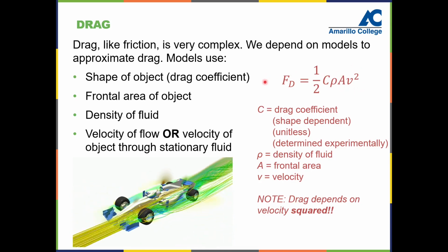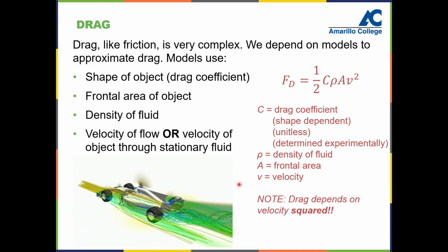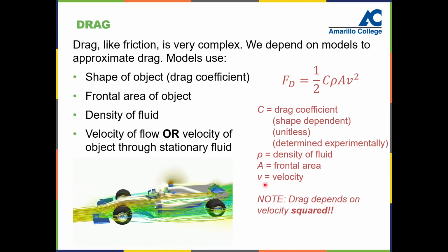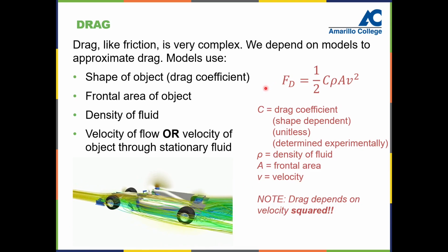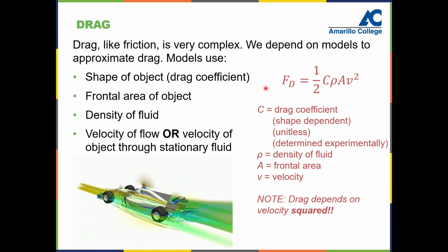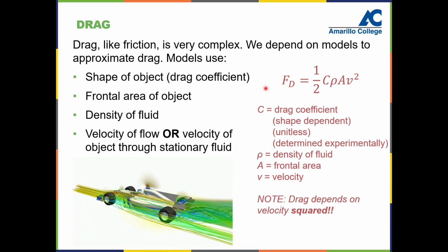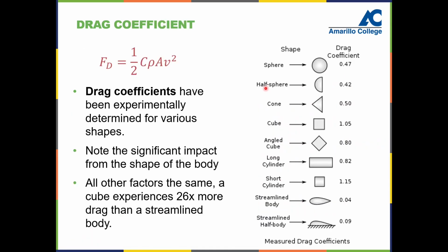So the velocity squared is proportional to the force of the drag. That means as we increase the velocity, the force of the drag increases with that velocity squared. So the force actually grows parabolically with velocity, not linearly like it does with the other constants.